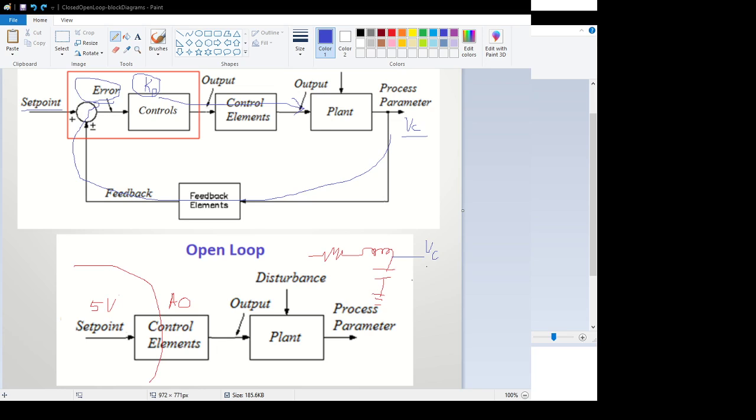Right now, in this video, I'm going to use 5 volts, so you could argue I could have made it an integer, but you want to have the flexibility to make it a fraction, so you need to make sure it's a value of real. Your error definitely is going to need to be a value of real. And then the control signal we're going to send out is going to be multiplied by the gain, so we definitely want to make that a real value.